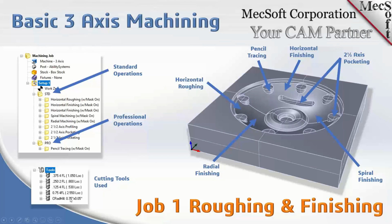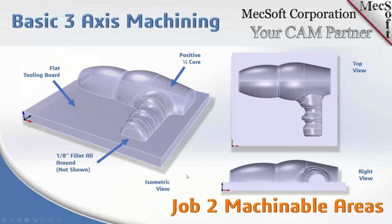And a quarter radius mill. That's a good point, because when I show you the bottle, there are some fillet radiuses in these areas. Like this first slot, there's a radius in the corner that we don't want to machine out. So we have a corner radius mill that we're going to use. We're finishing those areas, and there are fillets in this area around here as well. Okay, so let's go ahead and look at the next project.